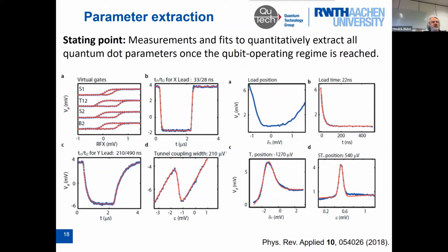Now, before elaborating on that, here we took the approach that rather than using imaging or charge diagram interpretation, which is always somewhat qualitative, we used a number of physically motivated measurements that can extract the parameters from the devices and define a set of characterization procedures that can then give the input target parameters, or the values that are compared to the targets for tuning up the devices. I'll briefly walk you through that.